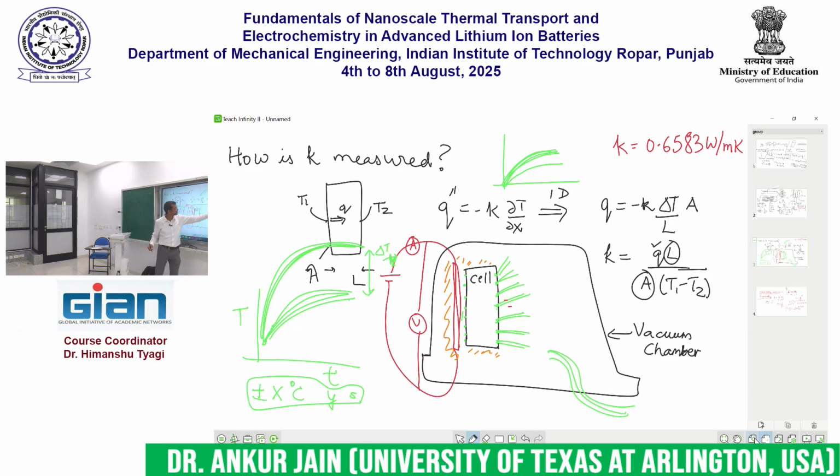See, from this equation, K should be a constant, right? So if Q goes up by 2 times, T1 minus T2 should also go up by twice, right? So you should verify that. That's an excellent suggestion, right? At some point in time, if you start passing too much current through it, then the temperature rise will be so high that the thermal conductivity, which in principle is a function of temperature, will begin to show its temperature dependence, right?